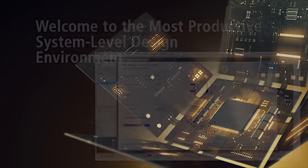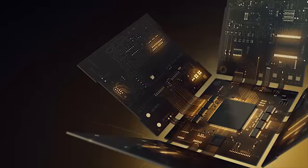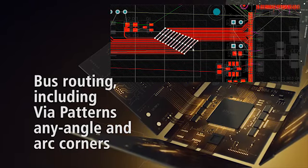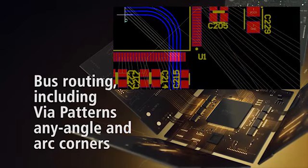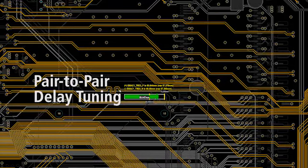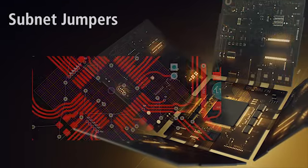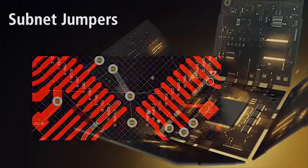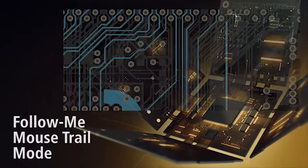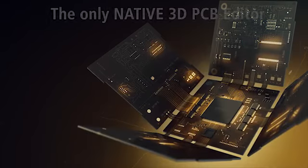Altium's goal is to make the best PCB design software available with advanced interactive routing with autocomplete, any angle routing, bus routing including via styles and arced corners, high-speed differential pairs routing, pair-to-pair length and phase tuning, net class length tuning, automated pin and gate swapping with subnet jumpers for auto completion, hug and push routing modes, follow me modes, intelligent push and shove,